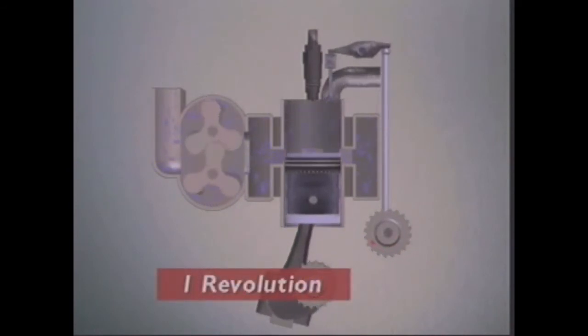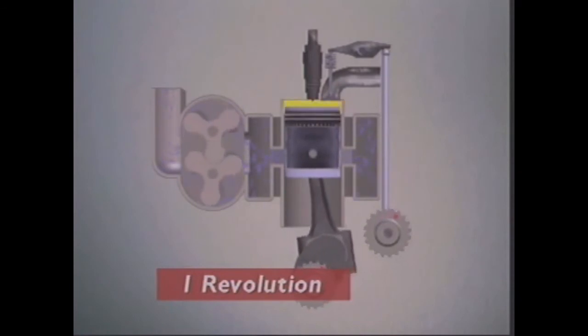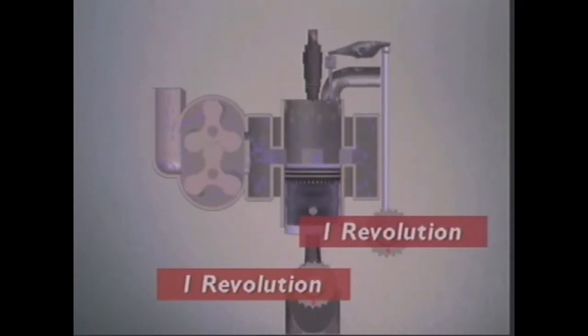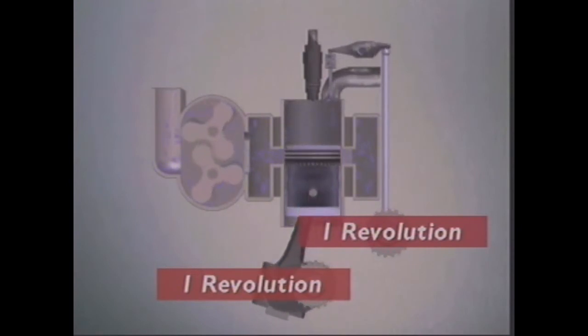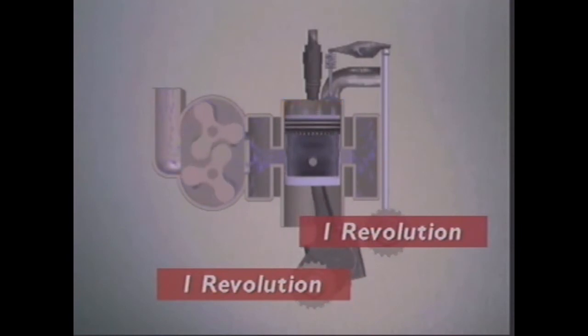It makes one revolution. During that revolution, the valve opens and closes once. The camshaft makes one revolution too. Camshaft and crankshaft must rotate at the same speed. The gears must be the same size.